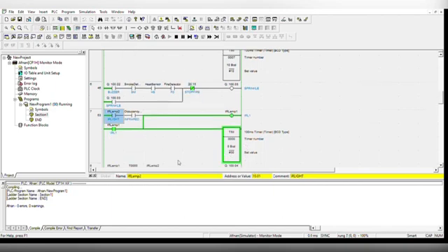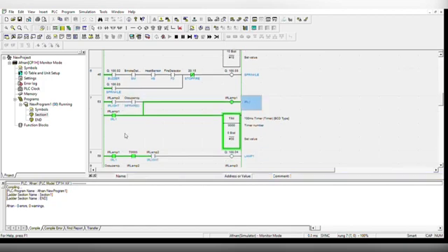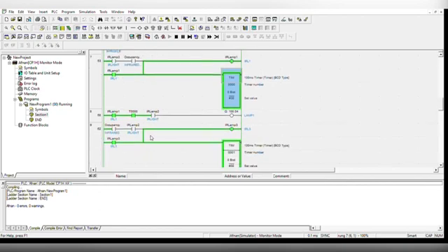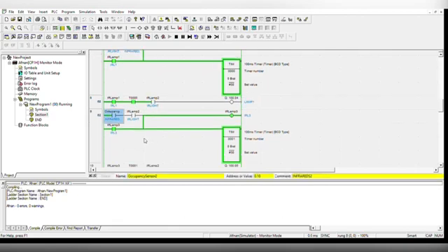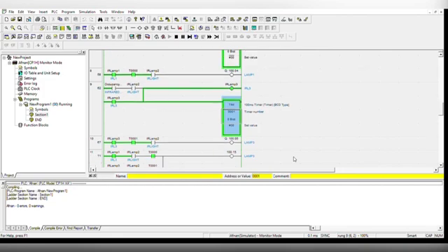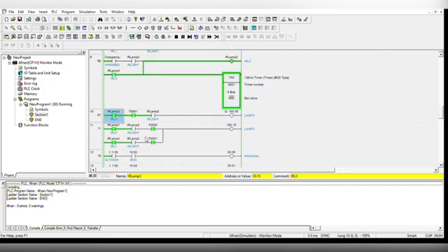Next, we proceed to the light, where we have the IR light and the infrared sensor for the occupancy, which relates to opening IRL1, which is lamp 1. Lamp 1 will also have a timer. When lamp 1 is open, lamp 2 will also open. And when infrared sensor 2 is on, it will light up light 3 and we have a timer. So when we have light 3 and lamp 2, it will turn on lamp 3, and when lamp 1 and lamp 2 are on, it will light on lamp 2.